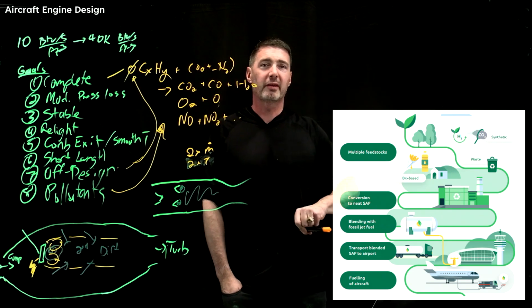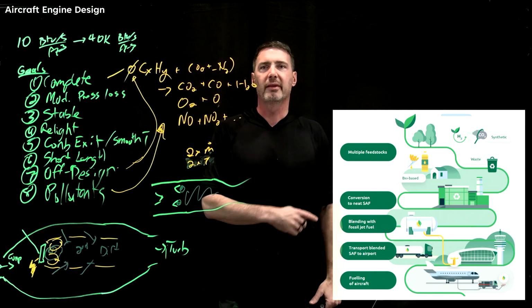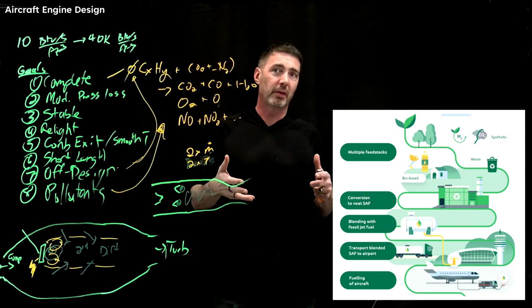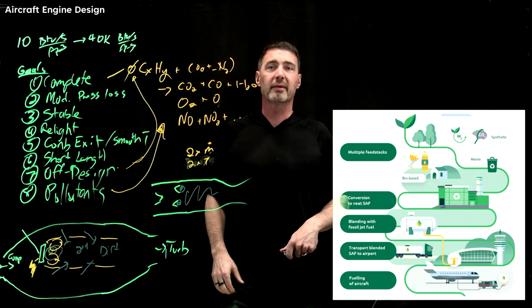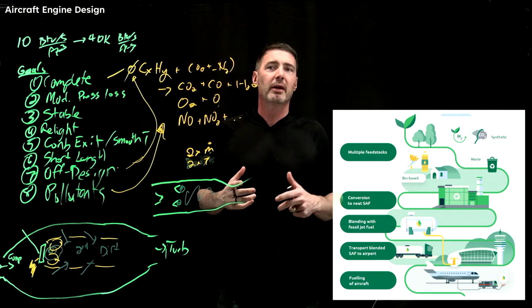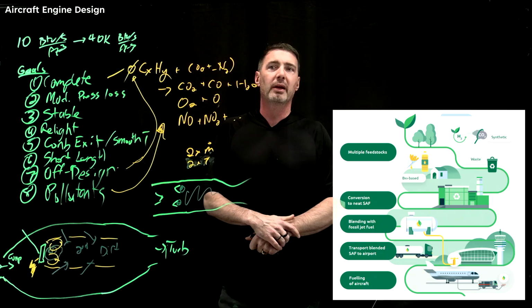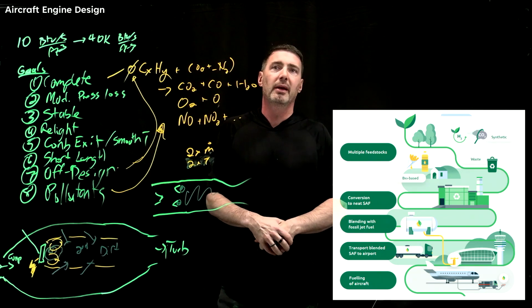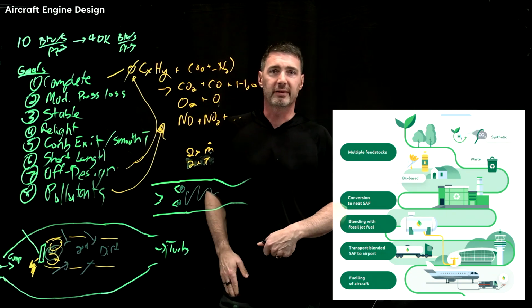And the start here, this part where it says blending it with jet fuel, that actually comes back to the combustors. So in the end, SAF is a different blend of all the little bits and things. It's kerosene with a slightly different blend, and a lot of the combustion stability is actually due to those very particular blends. So that's a lot of what they're doing right now, just trying to blend the SAF where the existing engines don't need any modifications. It's a very different story to then develop an engine, which is really developing the combustor to take pure SAF. Running a pure SAF engine is slightly different.